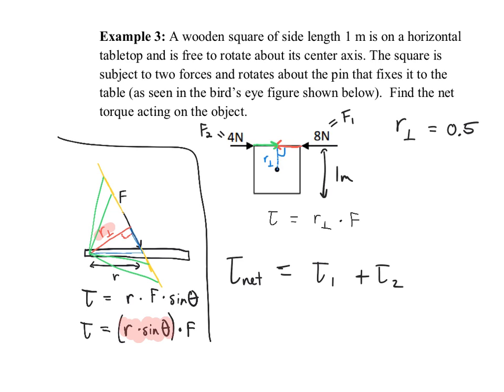It's fixed in the middle, so my fingers are holding it. Look, when I push in this direction, there's the rotation. When I push in this direction, it's the opposite rotation. That's why one of these will be positive and one of these will be a negative torque in this problem. So yes, F1 will cause a counterclockwise rotation, which is positive. So this remains positive as torque 1. Well, if that's positive, then the other one must be negative.